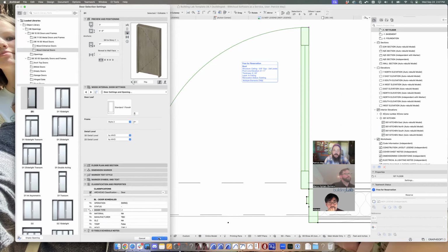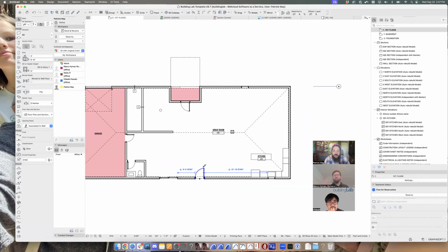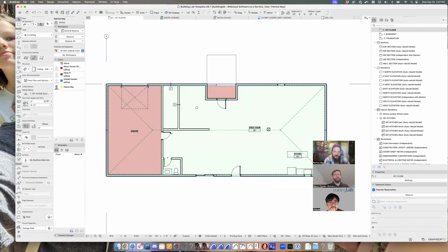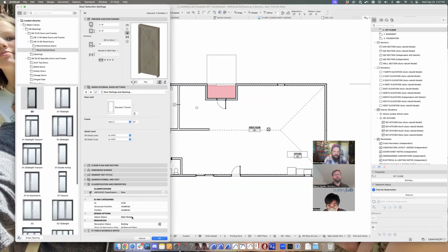So the nice thing about that is that's actually one of the most efficient ways, because then you're not going line by line in the schedule. I can grab all of my swing doors here and know that these all have to show as the same style, right? So then I reserve those. I go to the settings and I say that these are our door style.